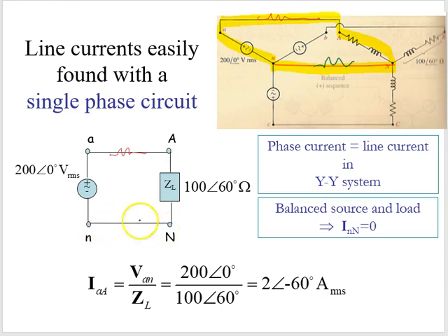This NN here is not really here. We've just drawn it in so that we have a complete circuit in order to analyze. So if we do have impedances on these two wires, we would have to consider this one. We'll call it RAA, but we would not consider our NN. So that's key. It's not going to be key to this problem because there weren't any impedances.